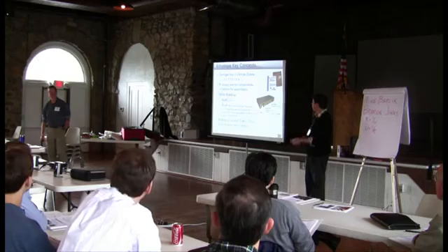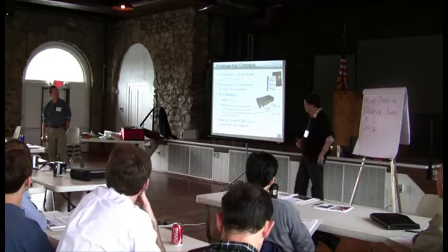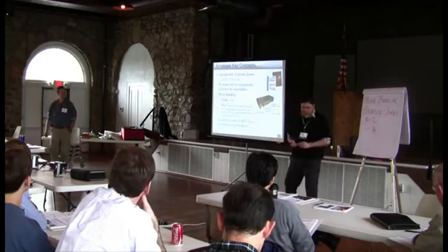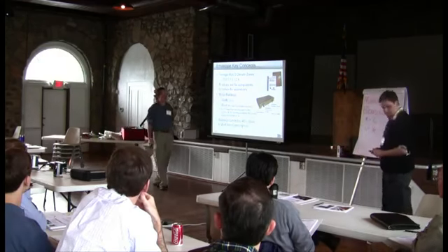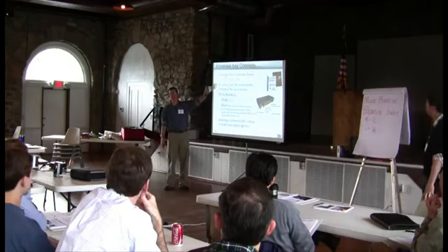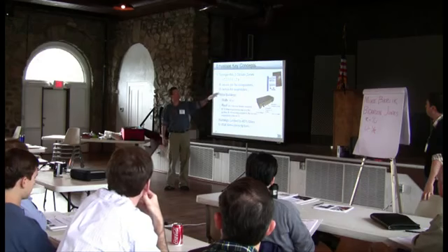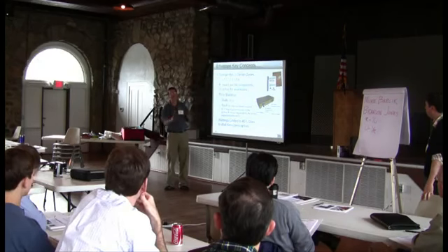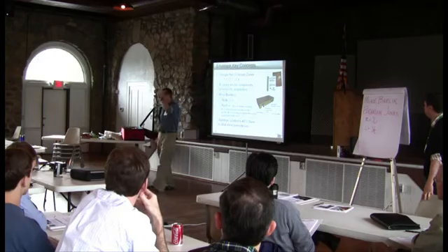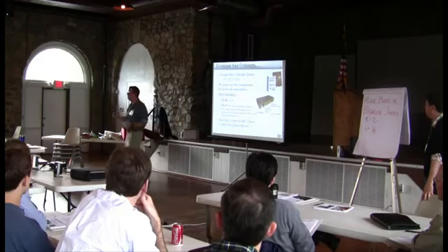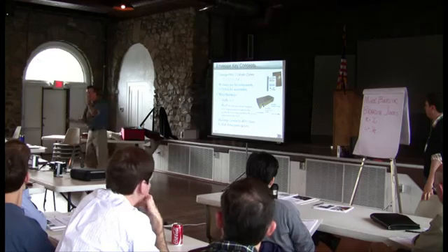You're like, why can't we just have one? But at the end of the day, in the prescriptive code, it'll give you an R value for, say, the wall insulation batt. Or it says you can build an assembly that has a U factor that's no worse than this. So we want a high R value, we want a low U factor, right? The lower the U factor, the less the conductance through the material.